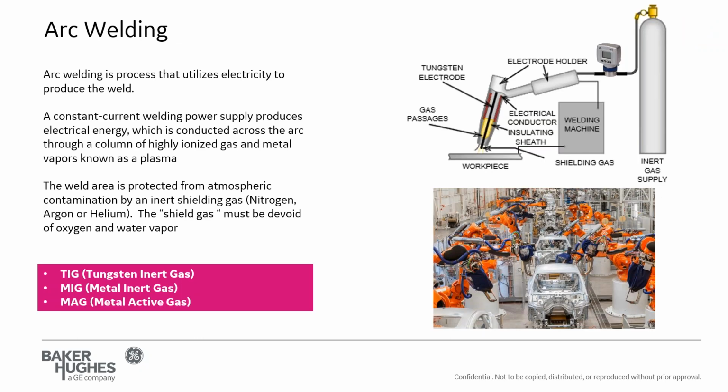So as I mentioned, welding, particularly in TIG and MIG welding, and today a lot of the welding is done through robotic welding, robotic arms. So at the tip of the weld tip, that is flushed with an inert gas, usually argon or nitrogen, to protect the weld from oxidizing rapidly while it's hot, so to speak.